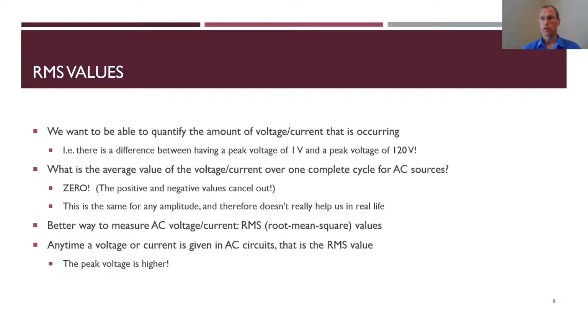And so the first thing you think of possibly doing is just taking the average voltage. Problem with that is the average voltage is going to be 0 no matter what, because you have alternating parts of positive voltage and negative voltage. So no matter what, they all average out to 0.